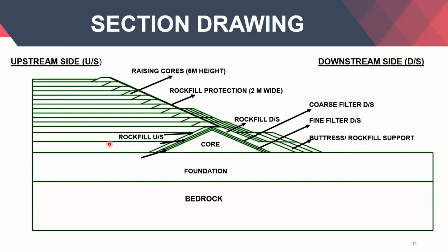At first, the three depositions are of around 12 to 12.5 meters, to a max of 15 meters height, one, two. Then the rest of the depositions are of 6 meter height. So these 6 meter height depositions coincide with the fact that each raising core is of 6 meters. So one has to understand the dam can only be built after the deposition has been done, and then we apply a water cover to it. In terms of FEM numerical modeling, we call it a nodal head.